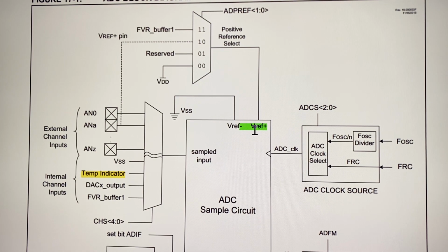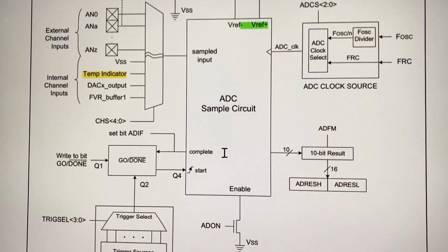And you might really need another type of sensor, for example a sensor that provides 0.5 volts to 3 volts, and you want 0.5 volts to be equal to zeros in binary code. So you will need a signal conditioning circuit, and that has to be external, made with external operational amplifiers or op-amps.